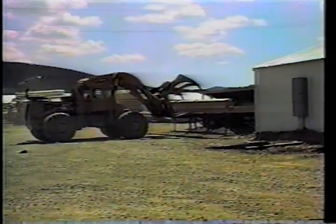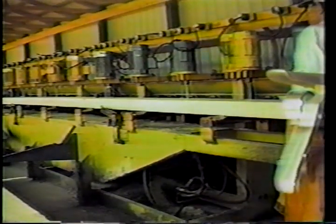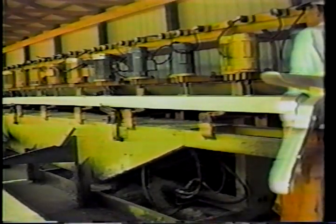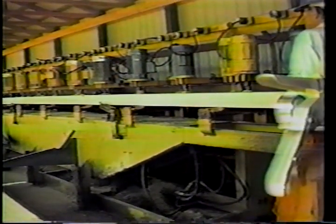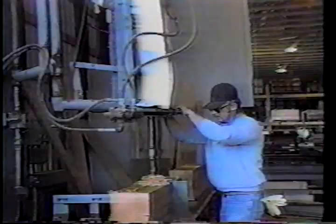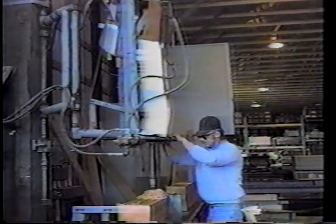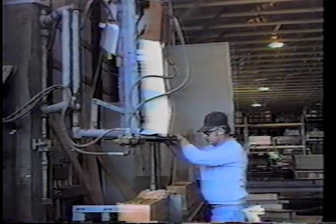Timber is unloaded and a treatment process begins. First, the wood is incised to give a pathway for the treatment material, and then trimming begins to occur. Notice that all of this work is done prior to any chemical treatment of the wood. The wood is well peeled, and all machining is completed before the actual treatment process. Machining to include incising to improve the preservative penetration, as well as the operation of cutting, framing, or drilling of holes.